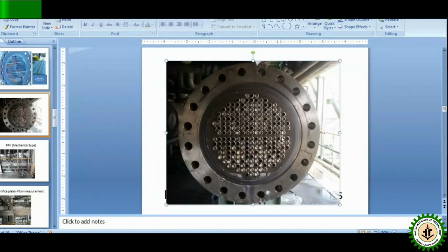blocked. Okay, so once any heat exchanger is in operation, you have to calculate the heat transfer coefficient. You know this concept of UC and UD, then the dirt factor, UC minus UD over UD times UC, and this concept of dirt factor. So you have to calculate this overall heat transfer coefficient, and you have to see how the overall heat transfer coefficient is changing with respect to time, with respect to operation. There will be some natural decay, there will be some forced decay.